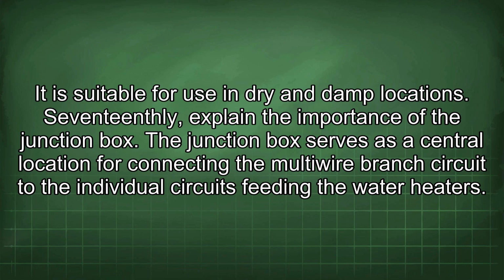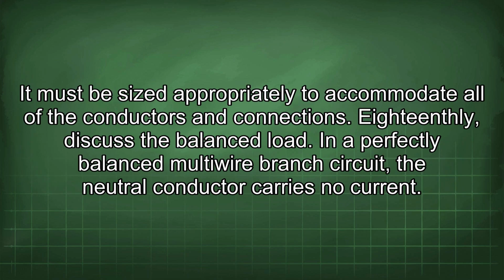17th, explain the importance of the junction box. The junction box serves as a central location for connecting the multi-wire branch circuit to the individual circuits feeding the water heaters. It must be sized appropriately to accommodate all of the conductors and connections.